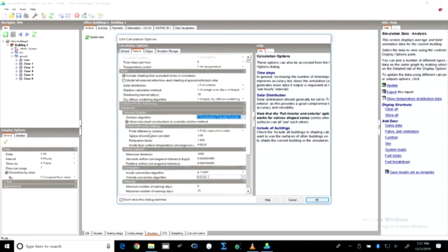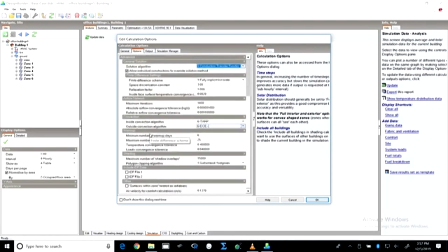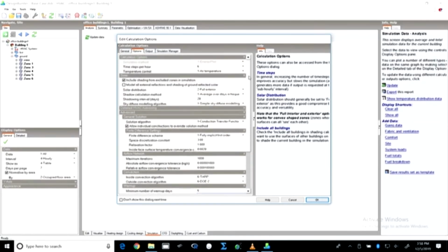When we are looking at the warm up period, we are looking at a minimum of 6 warm up days before the system achieves certain temperatures and the envelope is heated. Warm up days are the days where the building would have been simulated for these many days and the structure would have gained enough warmth to take into account the heat exchange because of the envelope. All this is included in the advanced details for the simulation.